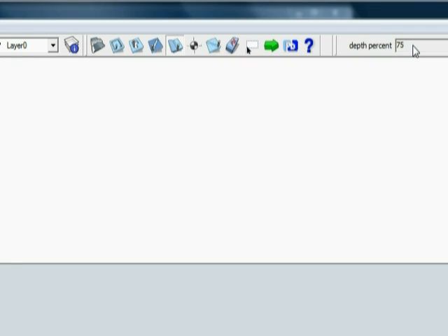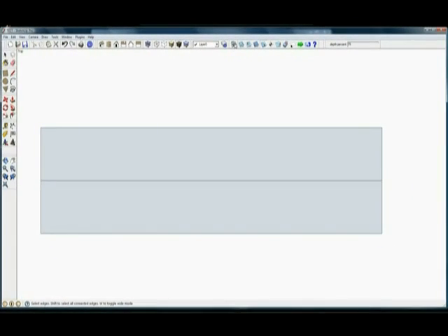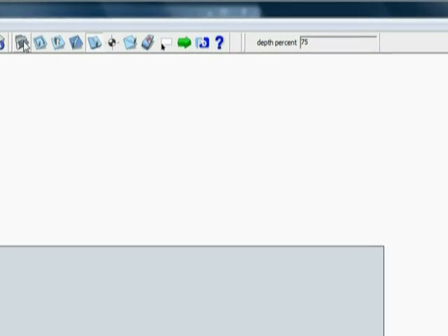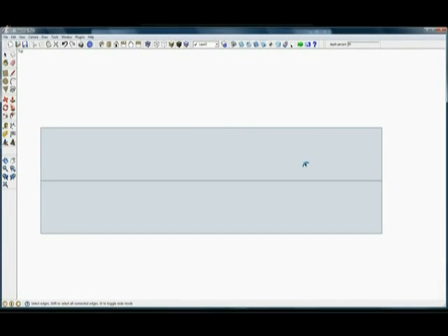And those percentages are going to be percentages of the thickness of the foam as we have previously specified in our parameters window. And you may recall I've set this thing up so that I'm cutting a 1/4 inch material. That's the substrate thickness that I'm using. So I can simply select by toggling through the D what percentage I want to remove of that foam, and then take my pointer down here, and you'll see that that line is going to highlight.